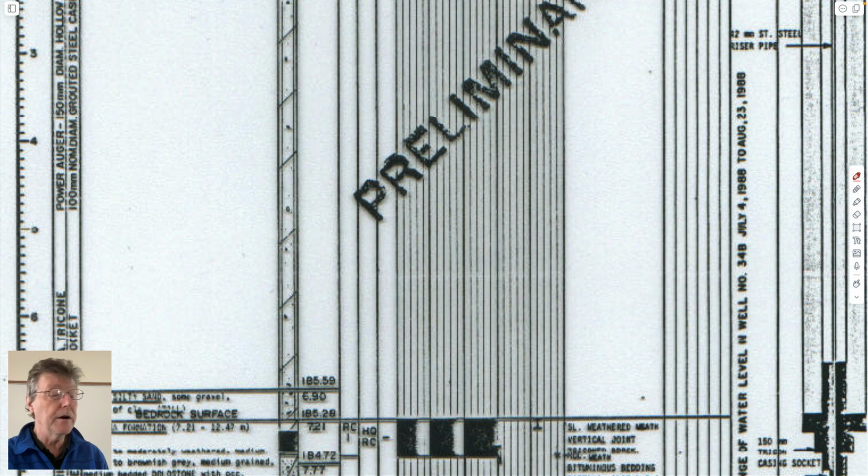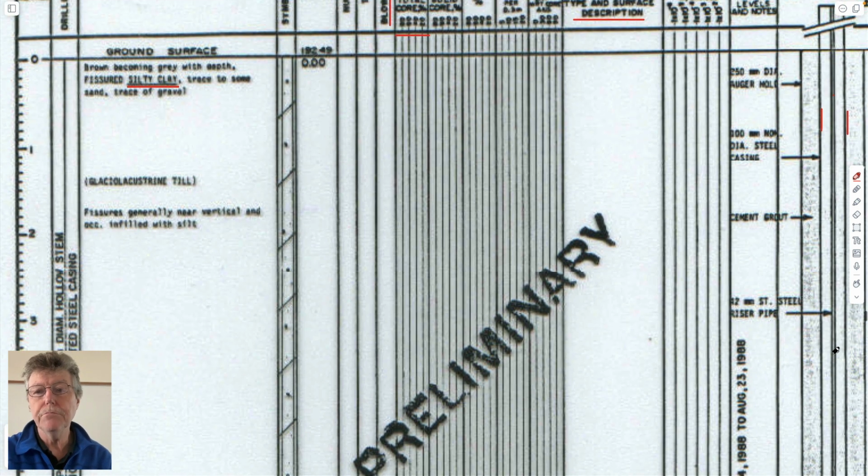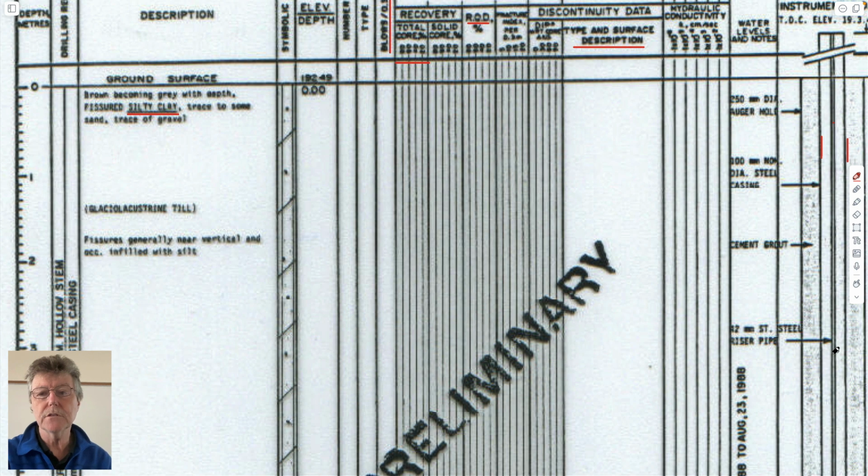So that way you're making use of your borehole, which might cost 10 to 50 bucks a foot, or 30 to 150 bucks a meter to drill, because you're leaving some instrumentation in it which you could sample water from to see what's dissolved in the water or what the free product is. You can also use it to get water levels upstream and downstream if you want to calculate advective velocities, if you have permeabilities. And you can also see how concentrations would change over time, because you can recover samples from it.